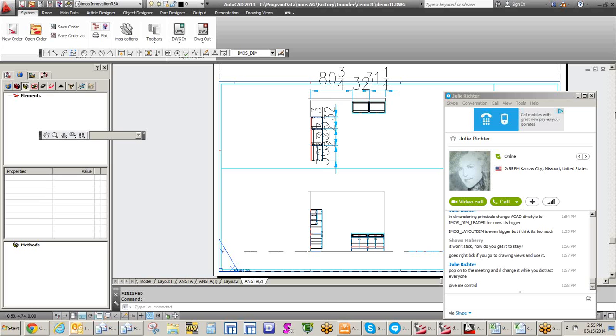But if you're using the 5D drafting, it does all of these things except it does not do planned sections of multiple products. And it doesn't allow you to automatically deal with the elevation sections where you want those to go. Just some of those basic things. And you can't control the direction that you want a section to go from. It only draws it one way.